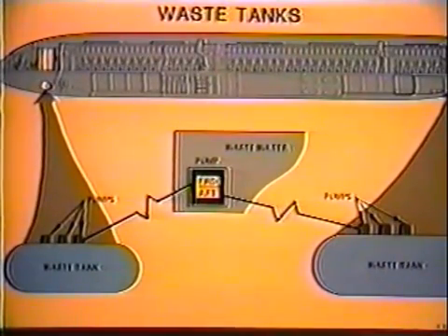Each system has 3 flushing pumps, which alternately respond to flush signals. If a pump should fail to flush a toilet when signaled, the controller will drop that pump from its sequence and illuminate the appropriate forward or aft wastewater pump light. The next pump in sequence, if available, will be signaled to operate.